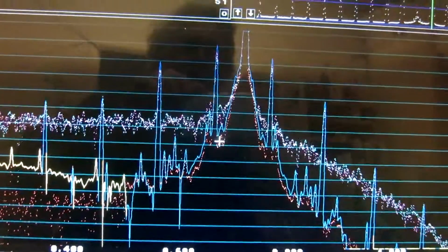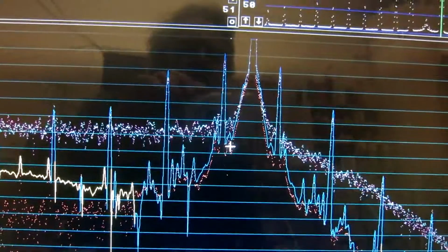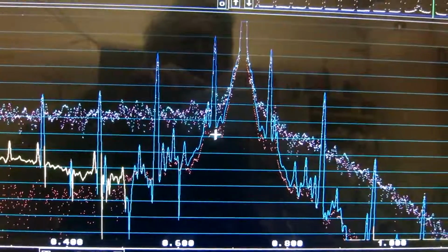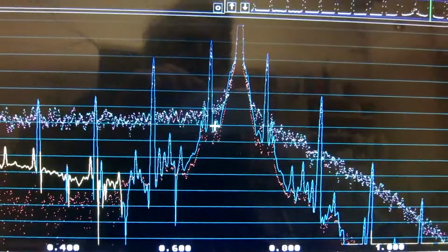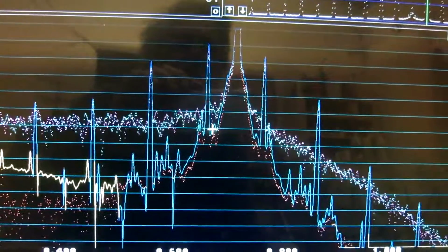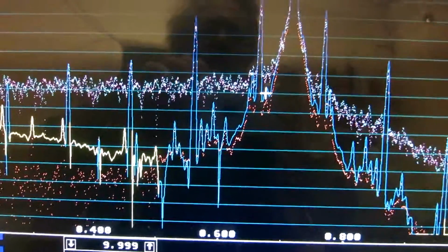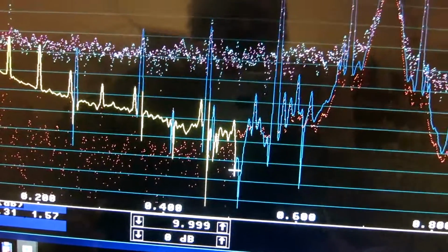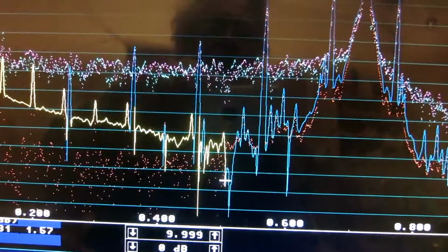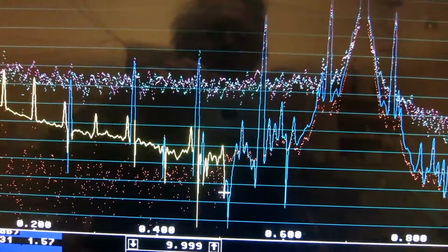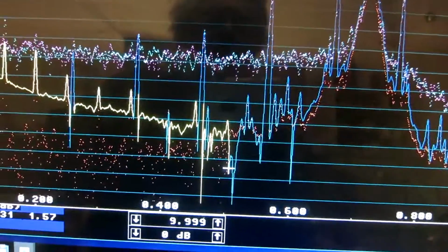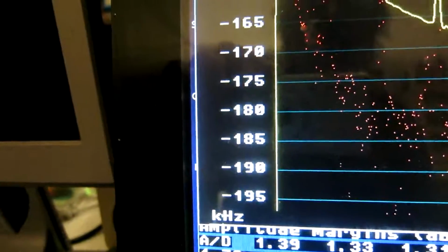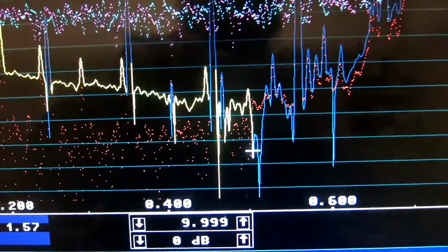And the phase angle is somewhere around 45 degrees. It means I see a strong signal in the imaginary part, and as it happens in the real part it's negative, so it comes blue. And this slopes fairly rapidly, and at this point here the positive and the negative component that goes into the real part happen to cancel each other. So I read artificially minus 190. That is of course not a true reading.